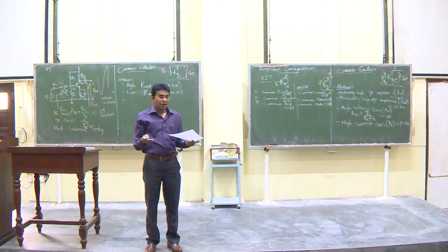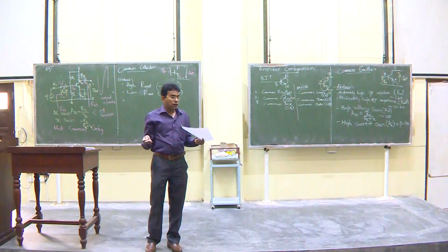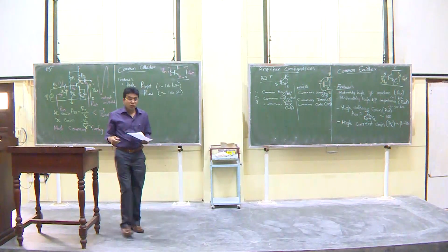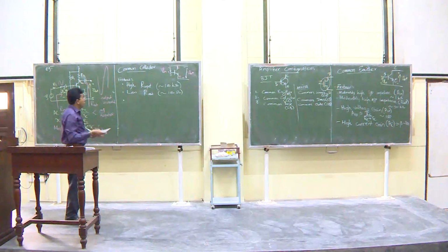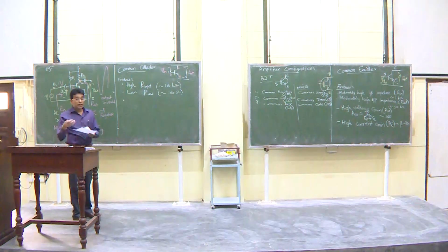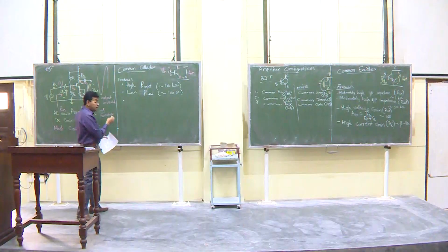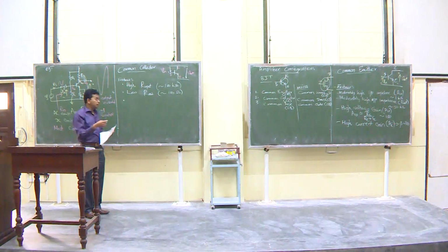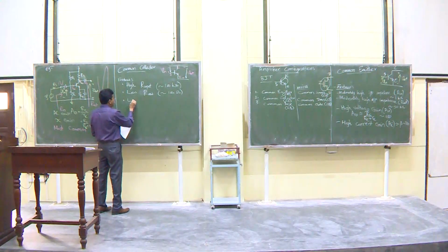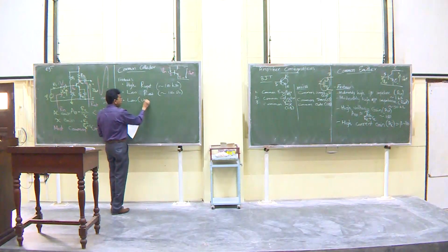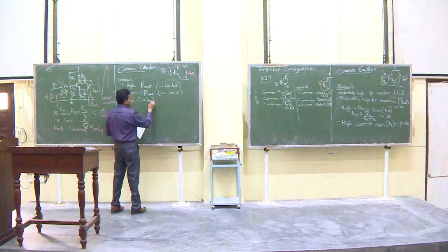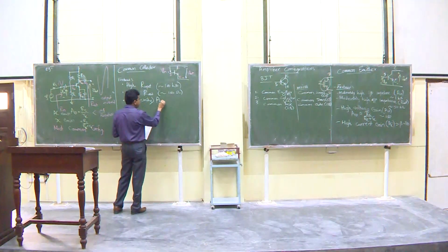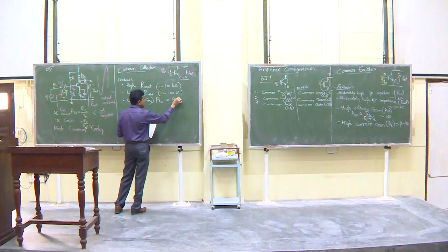Input and output not much different, maybe a couple of millivolts lower, but pretty much the same. So, if at all emitter is at a lower voltage than base. So, therefore, voltage gain is low, actually equal to unity and slightly less, right. So, low or unity voltage gain, AV roughly about 0.999,